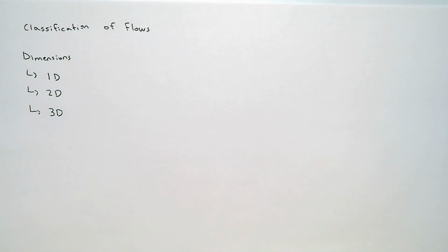And you'll find that sometimes it's easier or better or more efficient to model rivers in 1 dimension. Whenever I do my river models, I've done about close to 60 or 70 in Georgia. I've done more than 100 in other states. I'll mostly model them as 1-dimensional.